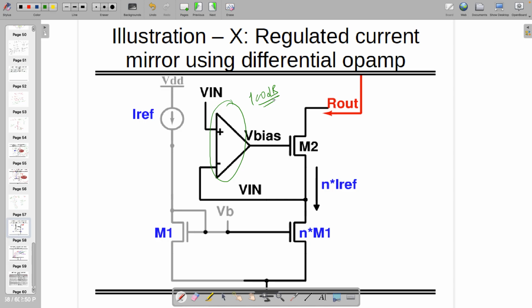So there you require such a setup, or the regulated cascode current mirroring technique is required, and this is truly used. All active probes have this thing inside them, right? Of course you need to make this triangle also. We'll study that anyway. So slowly we are moving towards that.